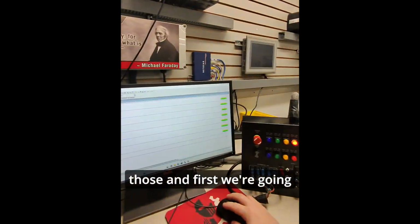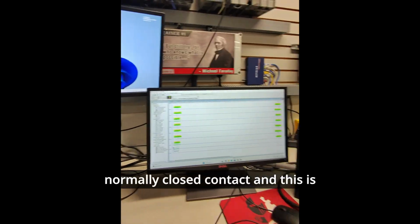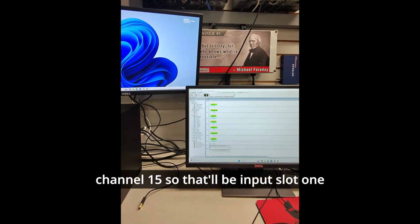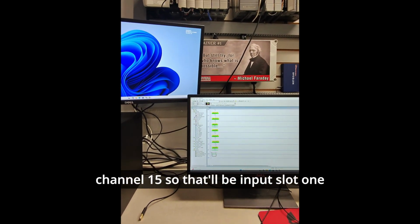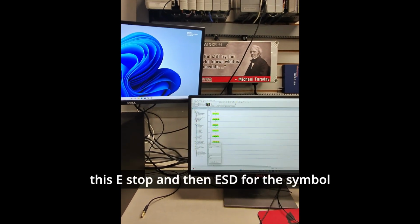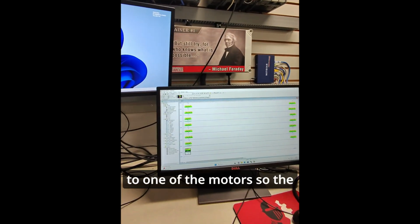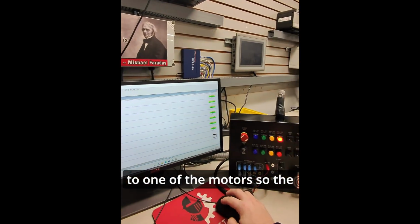First we're going to do the e-stop, which is a normally closed contact. This is channel 15, so that'll be input slot 1, channel 15. We'll call this e-stop and then ESD for the symbol. And then we'll just tie that to one of the motors.